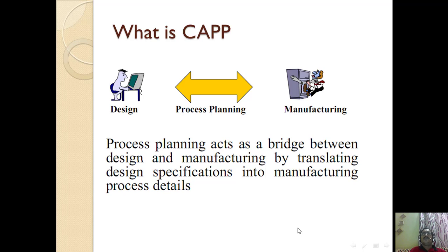Earlier, if the planning and design time was very high, then the machine would be idle. That affects the utilization of the machine. What is the definition of machine utilization? Machine utilization means actual machine working time divided by the total time. In those cases, as the machine will be idle most of the time because of designing or planning, your machine utilization will be tremendously reduced.